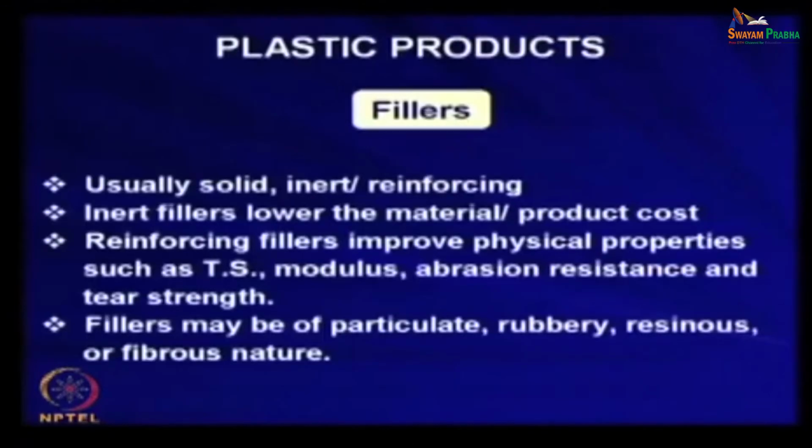So, there is improvement in tensile strength, and its hardness also increases, while its elongation at break decreases by incorporation of this filler. This kind of filler in rubber is known as reinforcing filler. So, if there is reinforcement of the strength properties of the base polymer, then we can call it a reinforcement.